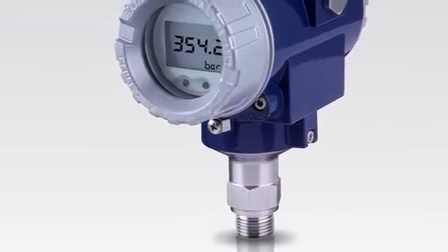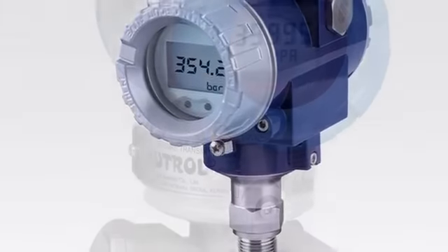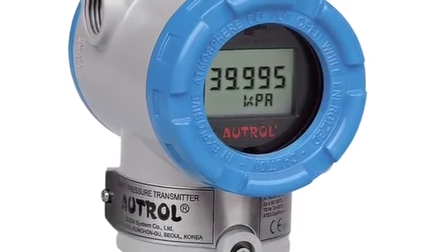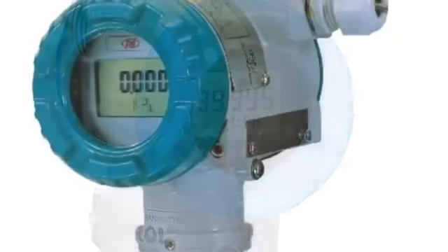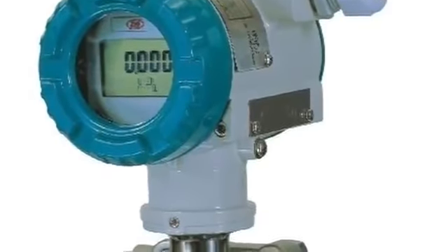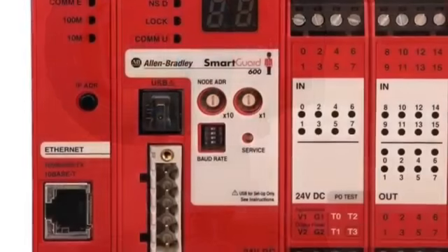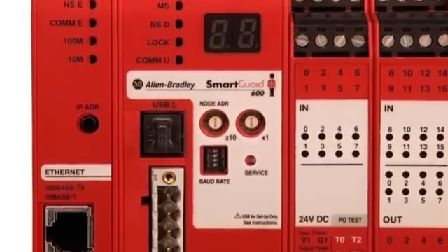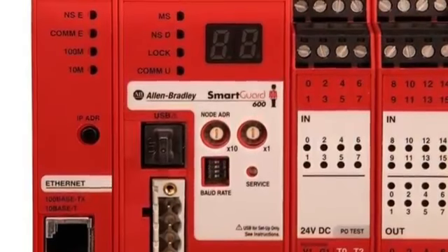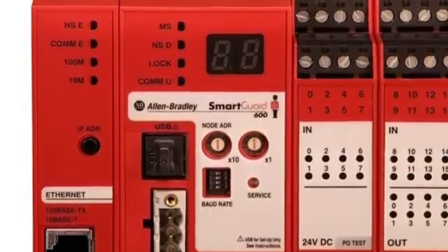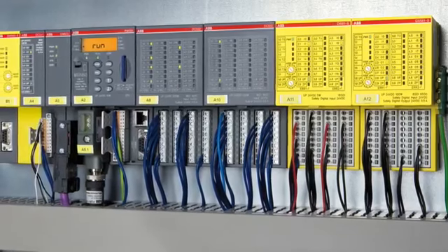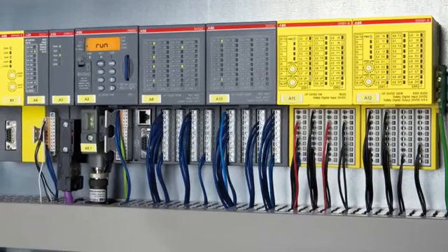Many major manufacturers provide process transmitters with safety integrity level third-party certifications to provide the industry standard 4 to 20 milliamp output. This analog signal retransmits the process variable to the safety PLC for analysis, where algorithms test to see if the process is within safe operating parameters. If abnormal conditions are determined to exist, an alarm may be sounded, and if dangerous conditions are confirmed, an emergency shutdown sequence may be initiated.